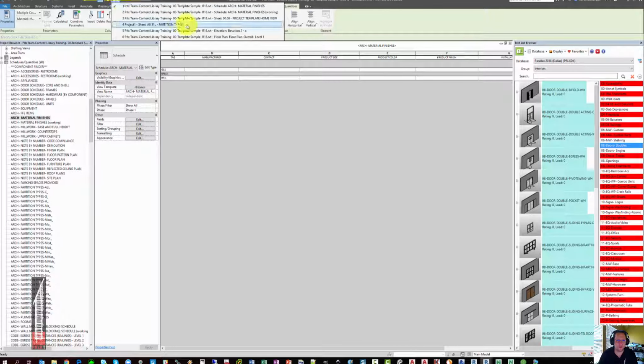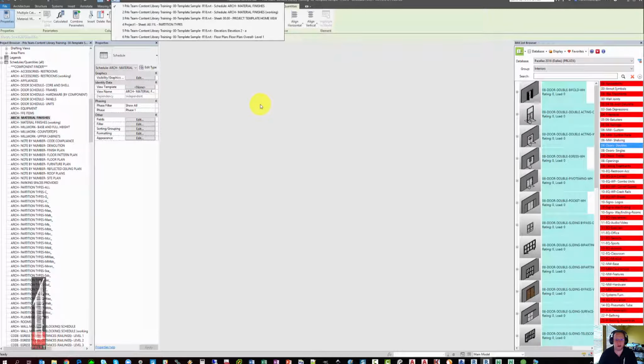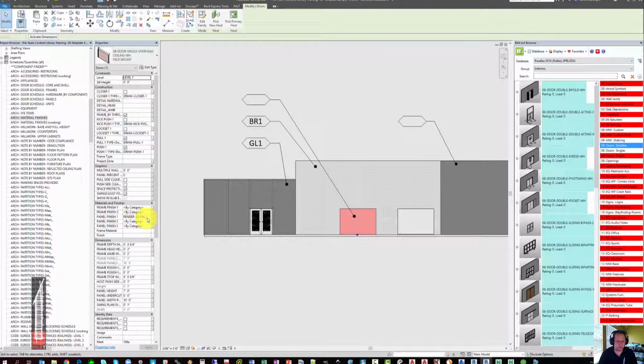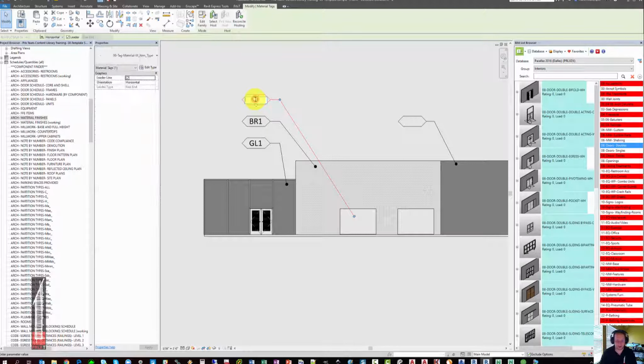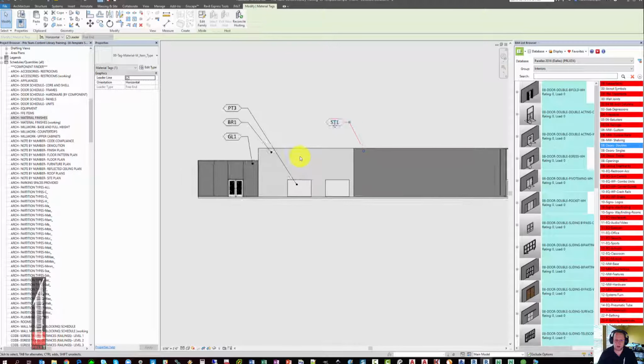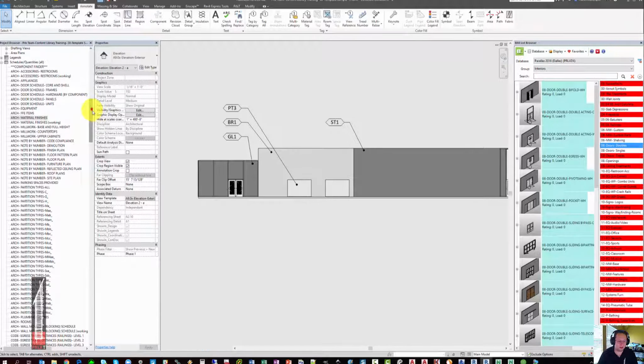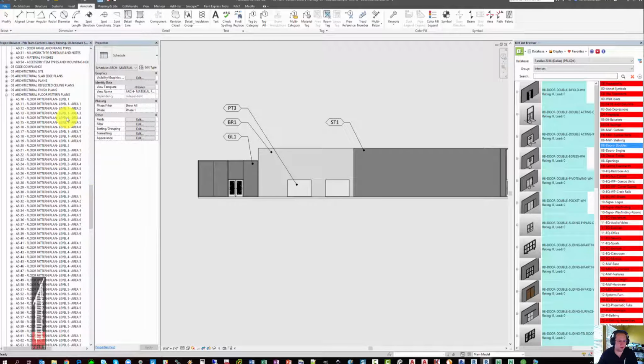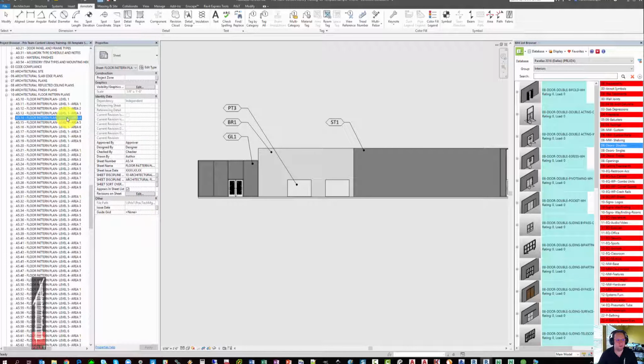Similarly, if we now go back to the exterior elevation and also fill in, for instance, on this door, we've already given it a finish material in the parameter of the door, and we may decide that that color is paint 3, and then we may also have stone 1. So we could do this for the rest of the building, and it's not required that these only be done in elevation, of course. If we were to go to our floor pattern plan,